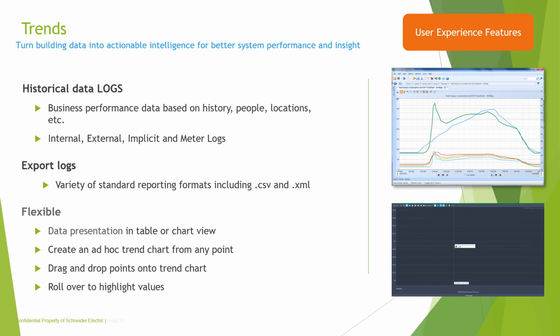Historical data logging allows us to record and store data from points in the system. Locally collected data can be sent to an extended trend log in the enterprise server, where storage capacity is typically larger. This frees up memory in local controllers like the ASP and gives redundancy to trend data.